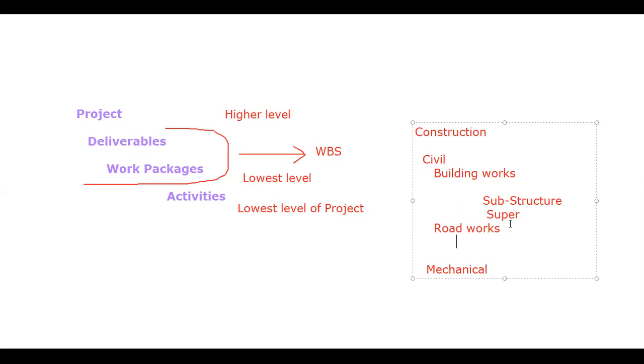So what is the purpose of the WBS? The purpose of WBS is to plan your project in a more effective way, to monitor your project, and to control your project in a more effective way. Later on, if I need something from substructure and I have divided my project into a proper WBS, then I can come into substructure and track the concerning activity. But if I have not broken down my project and all the things are under one label, then it will be very difficult for me to track or identify an activity.